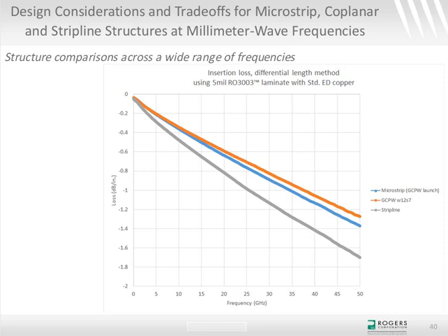Yeah, it does. And if you plate the gold thick enough, then it's just a battle over time more than anything else. And also temperature. If it's a hot application, then these oxides are going to grow through the gold even faster. But if it's thick enough gold, it lasts longer. So that's that kind of thing.